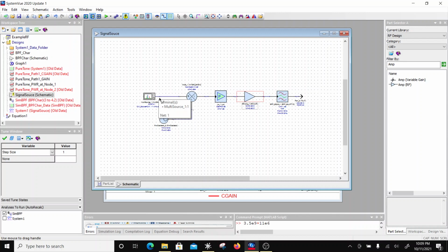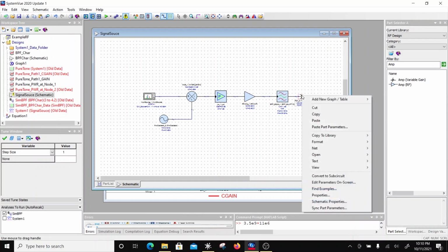So in case of a transmitter, you will not be looking at the noise, but in case of receiver, you will be more focusing on the noise, right? Here you are more focusing on linearity or the gain, right? Or the gain budgeting or the power. While in the receive chain, you are more concerned about the noise figure, right? And of course, you know, SFDR and things like that. So once I discuss that, you will have more insight into receiver side.